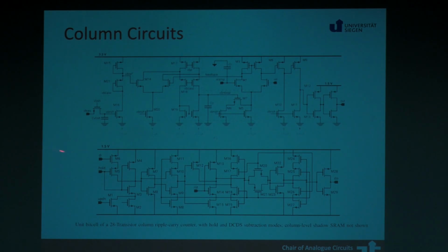And on this side we have some of the subtraction circuit. Remember, we have to do this subtraction between two signals, the reset and the bottom. We want to do that subtraction in the ADC as well if possible. So we have some more circuitry. It very soon becomes something like 120 or 200 transistors. And we are not even showing you the SRAMs which go in.